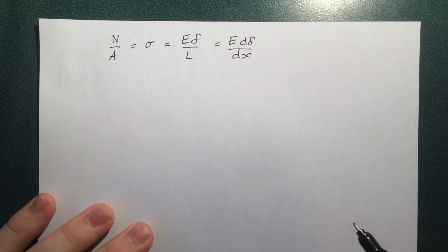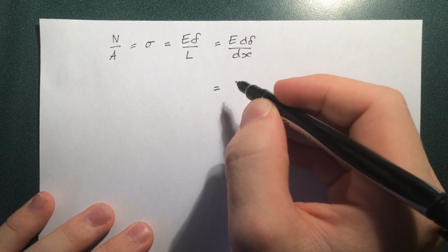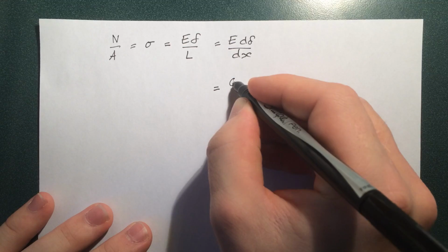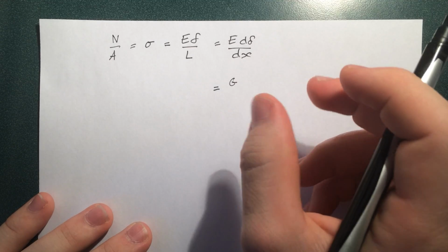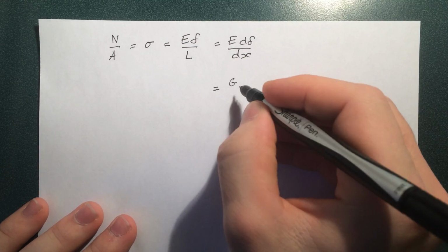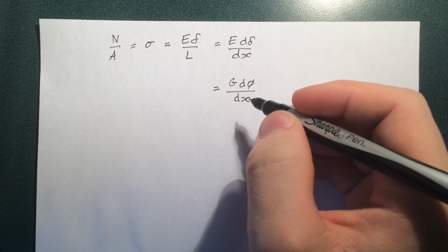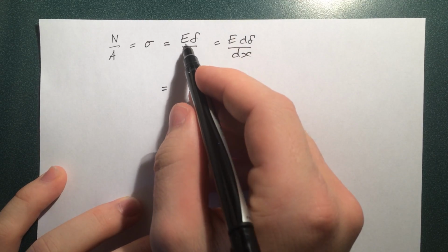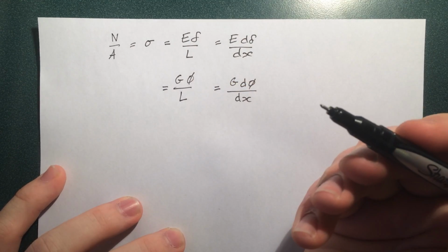So in torsional bar world, we have an equation that's pretty well identical to this in terms of similarity. So in torsional bar world, instead of a modulus of elasticity, instead of Young's modulus, we have a shear modulus. We'll call that G. Alright, now d delta here, that's an elongation. In torsional bar world, we have twist, so it's going to be an angle. So we can say d phi, and the dx here is still the same. Alright, and let's just go right through here. This is essentially the same, right? E is G, delta is phi, and the length of the bar, it's exactly the same.